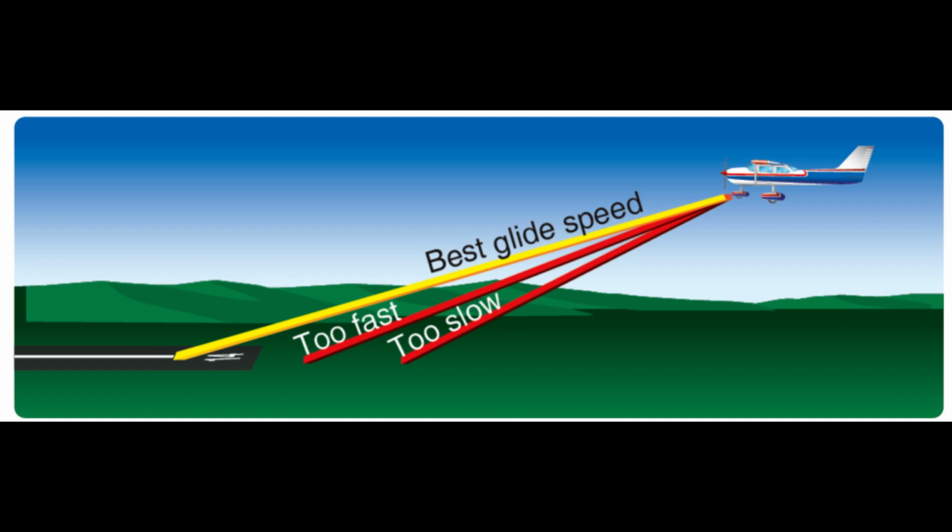When recovery is being made from a gliding turn to a normal glide, the back pressure on the elevator control, which was applied during the turn, needs to be decreased or the airplane may pitch up and experience a loss of airspeed. This error requires considerable attention and conscious control adjustment to re-establish a normal glide airspeed.